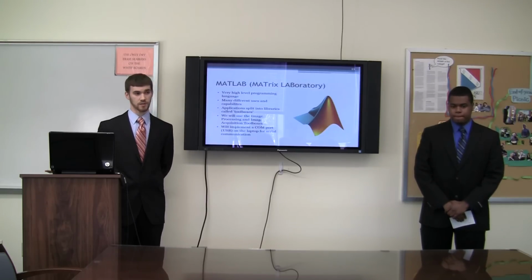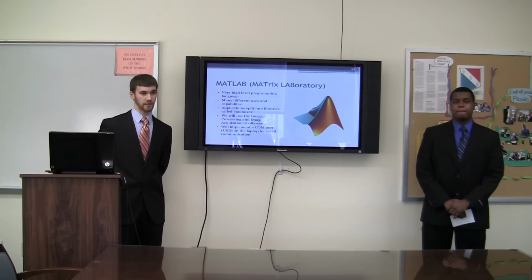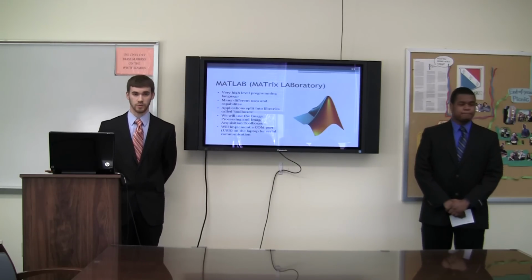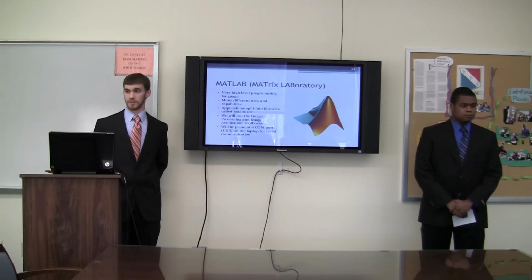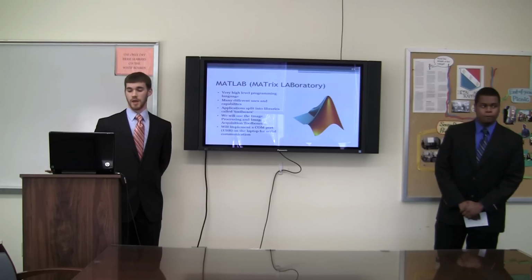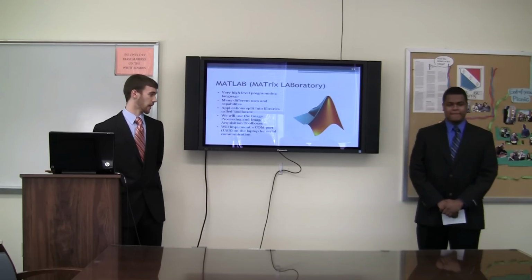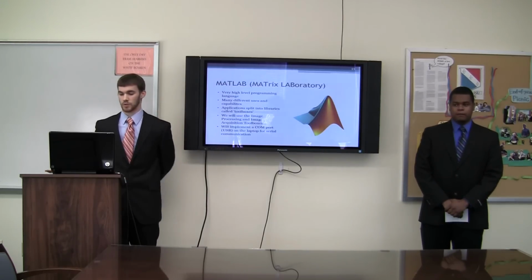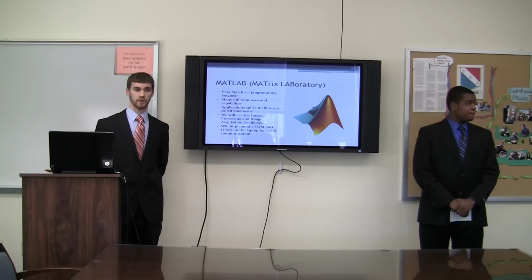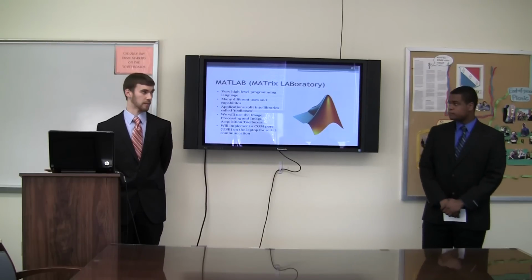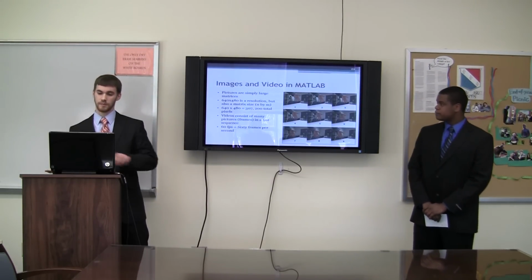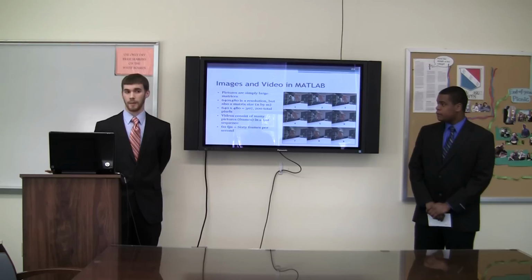The different applications that we can use with MATLAB are divided into libraries called toolboxes. The two main toolboxes we used were the image acquisition and the image processing toolboxes. We also implement a COM port, one of the USB ports on the laptop, to use serial communication between the laptop and the Max32 development board. Images and video in MATLAB.